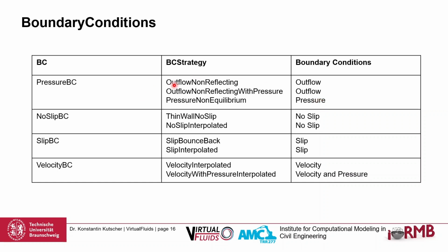And here in the middle are the strategies for the different boundary condition classes, you can say. For example, we have the pressure boundary condition class, which can be implemented with, in this case, three different strategies: outflow, non-reflecting, and pressure non-equilibrium.